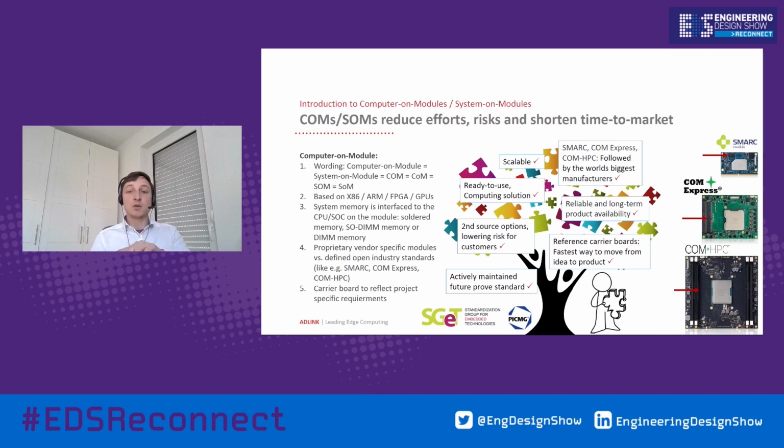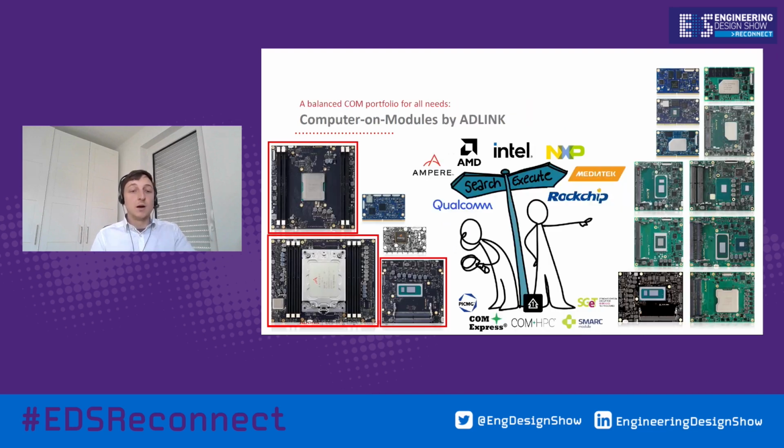The carrier board of the client can implement special I/O interfaces, additional memory devices, and connectors according to the application requirements, while the computer on module itself remains a commercial off-the-shelf item. So customers can really concentrate on their mission to contribute their core value proposition without wasting time on complex CPU and SoC implementation.